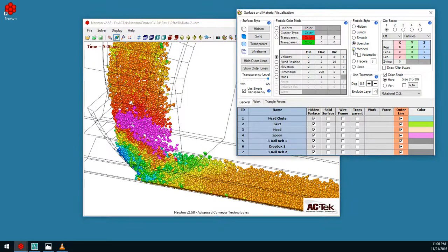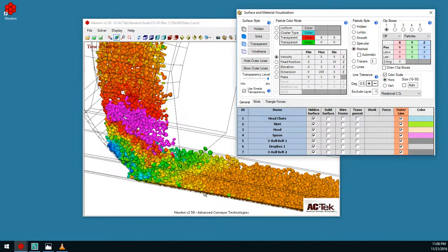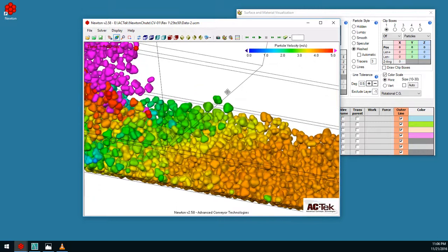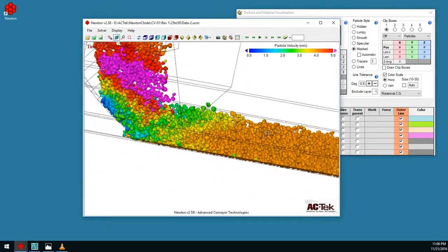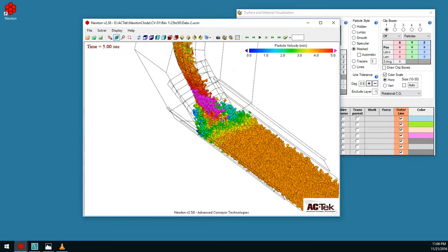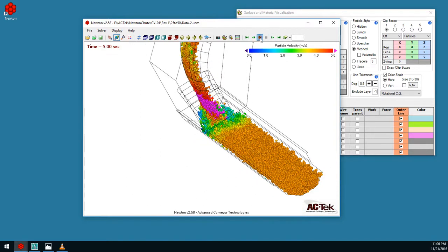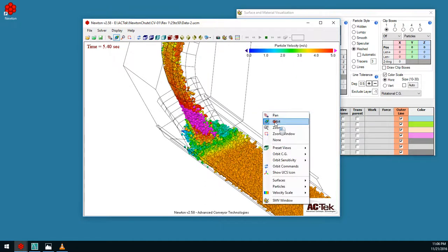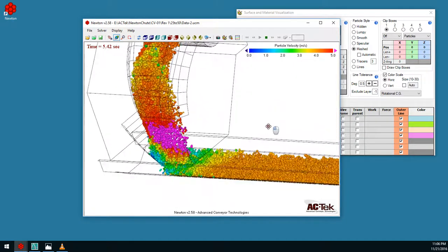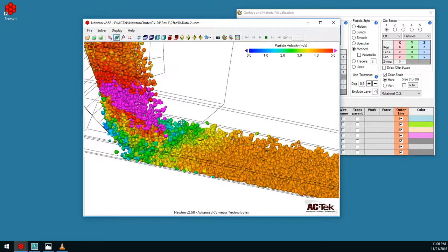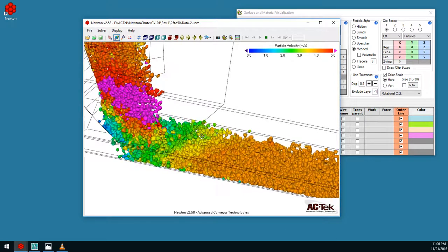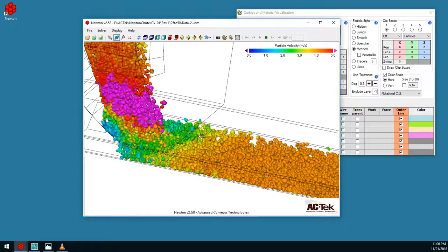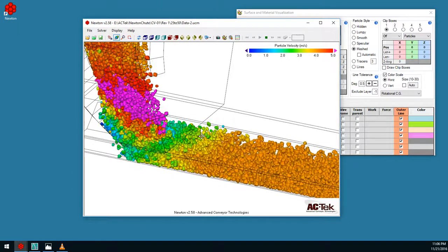Certainly, if we go back to our particle shapes, we can actually mesh our shapes. So you see here, all of our clusters become these nice, smooth, mesh type shapes, and there's again a number of tutorials discussing how you work with the mesh shaped particles. I think you will quickly find with DEM simulations, using strictly spheres is a problem because you can't get even simple angles of repose with spheres.